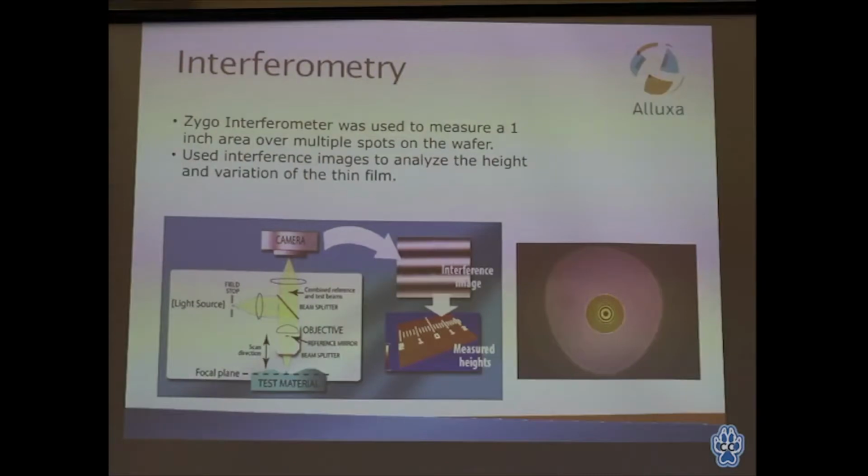Now, as you see here, I have an image of my substrate. This is actually the outer edge right here of the substrate. This right here is what I could get into focus with the curvature. That's how bad the curvature was on the substrate. As you see right here, there's this small yellow circle. That is called an aperture. I'm aperturing down the light; this is a 1-inch aperture, so I'm looking at only an inch in diameter of the substrate. With this, you can see that I have a really good image here, but out here, I have a lot of reflection, and I could probably align out here if I had to, which I did for some of the other measurements, as I'll show in the next slide.